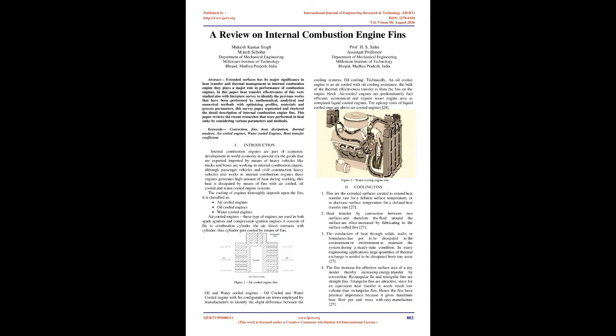The cooling of engines thoroughly depends upon the fins. It is classified as air-cooled engines, oil-cooled engines, and water-cooled engines. Air-cooled engines. These types of engines are used in both spark ignition and compression ignition engines. It consists of fins on the combustion cylinder. The air directly interacts with the cylinder, and the cylinder gets cooled by means of fins.